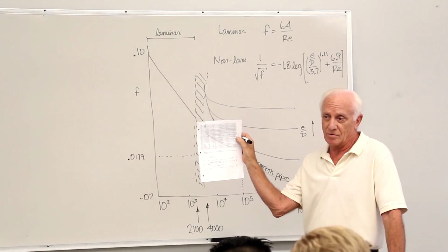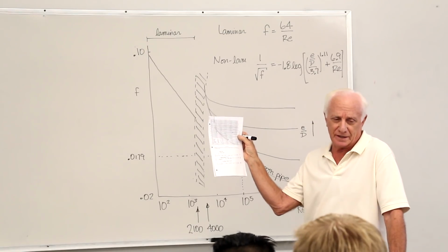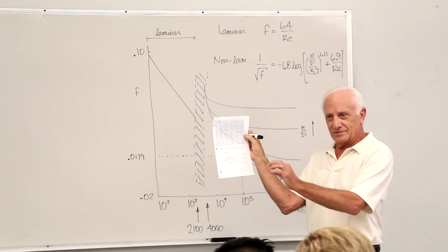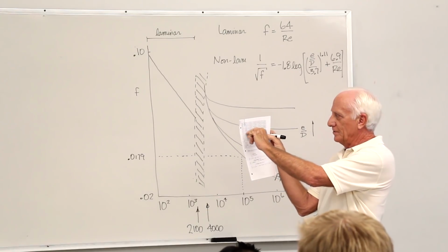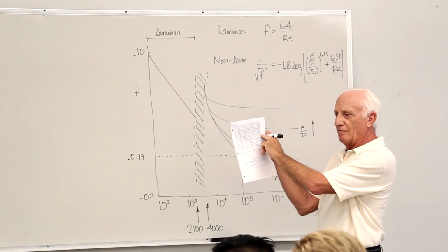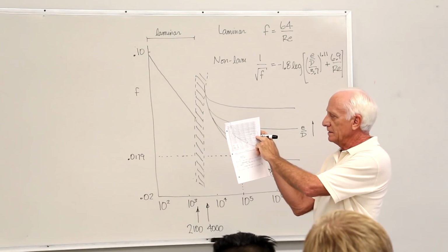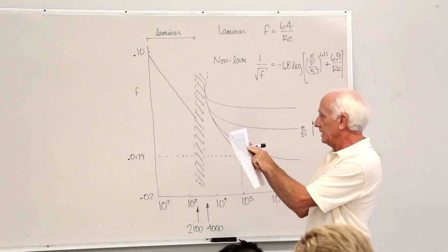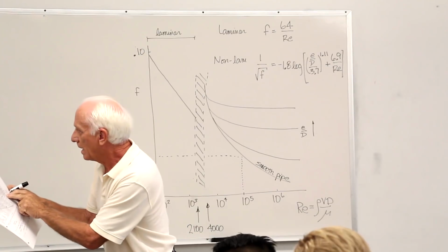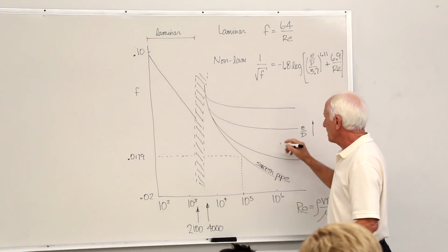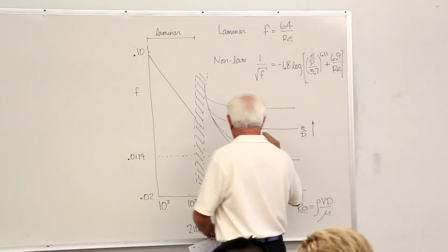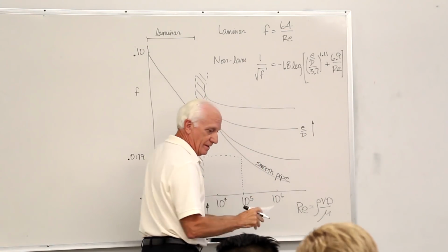Okay, so go halfway between is fine. Take your pencil, maybe draw a line along there between the 0.002 and the 0.004 on the E over D. The Reynolds number is 1.4 times 10 to the 5th. So it just started up from being horizontal. So it's right around here.